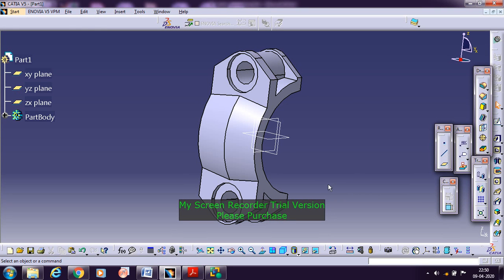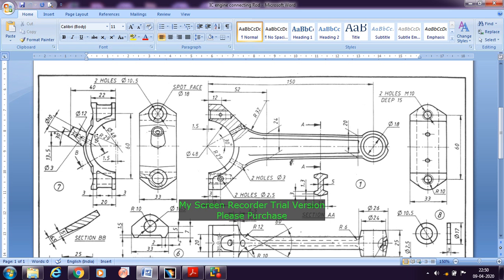So once it is done, now we can go with the oil hole here. For producing this oil hole, we need to draw one line anywhere, taking an angle of 30 degrees. Then, once after drawing this axis line at an angle of 30 degrees, at the end point you need to set the vertical distance to 13.5 mm, and then the horizontal measurement to 40 mm here.